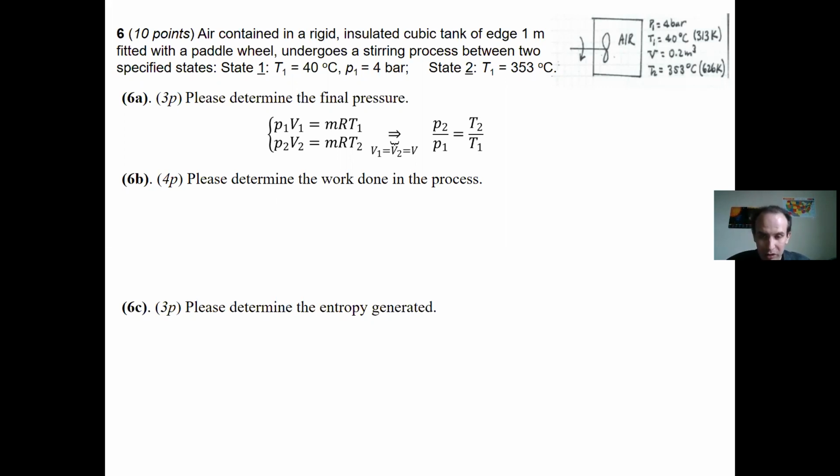But work is not just boundary. Remember chapter 2 in thermodynamics, we're approaching the final exam. Work is everything which is not heat. It's any energy transfer which is not heat. Here you have a stirring process. You do work on the system by stirring. You deposit energy in your device, correct? So work will be finite. It will not be boundary work. Or it might be an electric heater, which would be electrical work. Or it can be magnetic work. So work is not 0.